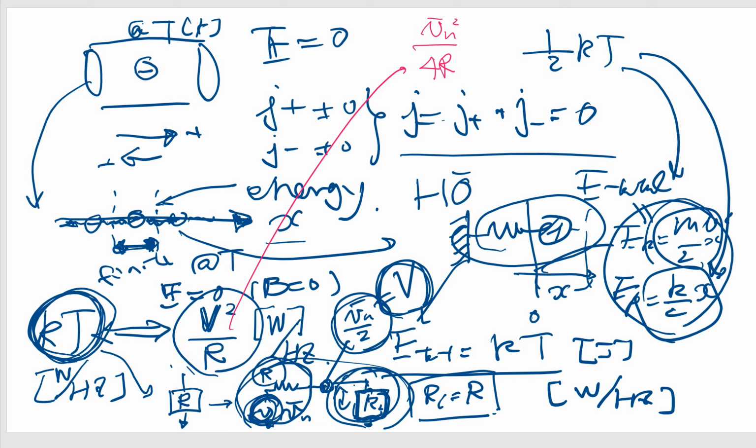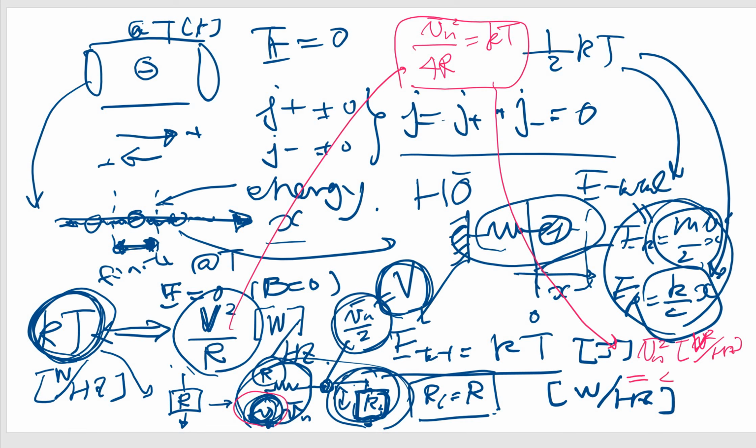So if the resistance has noise Vn squared, Vn variance, and the resistance is R, this is kT at maximum. Then you get Vn squared, volt squared per hertz, defined by 4kTR, with resistance R.